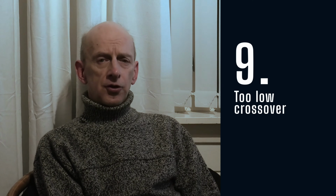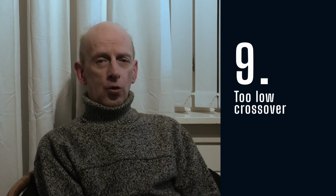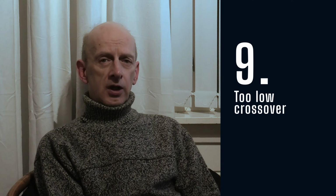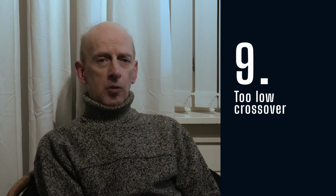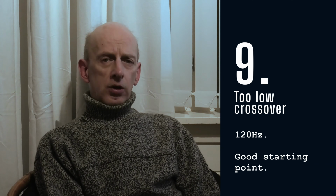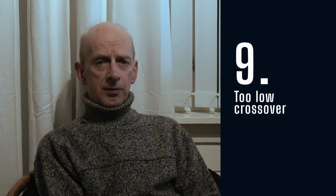Number 9 is too low a crossover frequency. Often you see 40 Hz or 60 Hz recommended and used, very common, and 80 Hz is then kind of the maximum upper limit recommended. My subwoofers are all made and recommended for a 120 Hz crossover, and there is a reason for that.